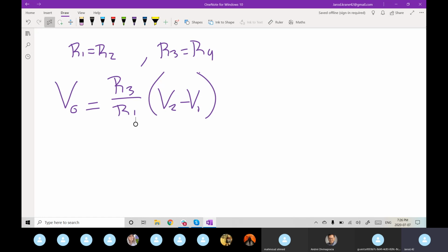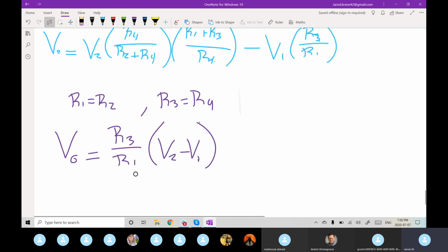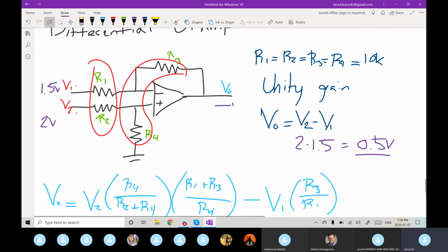Now this is where it's more used, because in the case of maybe they're just very fine signals, so instead of 1.5 and 2, we are running with 2.02 and 2 volts. So now we just have a difference of millivolts to detect. But if we were just to try to feed that directly to a microcontroller or something to pick up, maybe it wouldn't be able to.